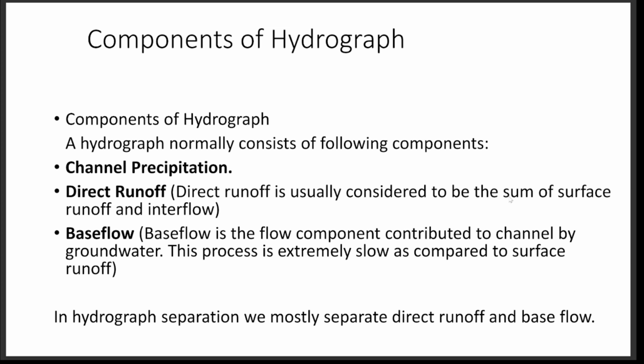Direct runoff is usually considered to be the sum of surface runoff, which is the rainfall water which is flowing above the surface of the ground, and interflow is the water which infiltrates through the soil to the groundwater.